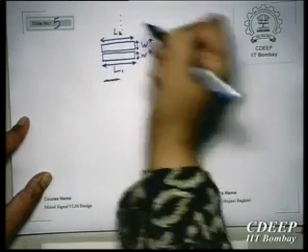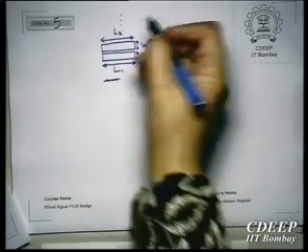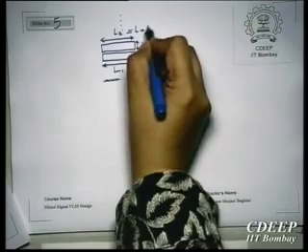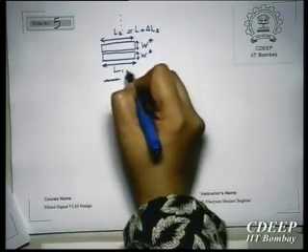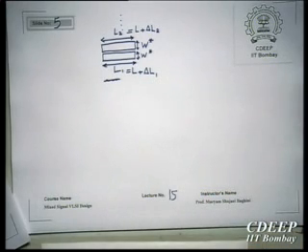I will continue. The whole point is, if I increase the number of strips, I am just increasing the area of my transistor by increasing W. I will get less standard deviation in the equivalent L. Each one of them is L plus some delta L. Intuitively also it is clear because you have more samples in your sampling domain. Therefore, your average will approach 0 and you will get the same L.